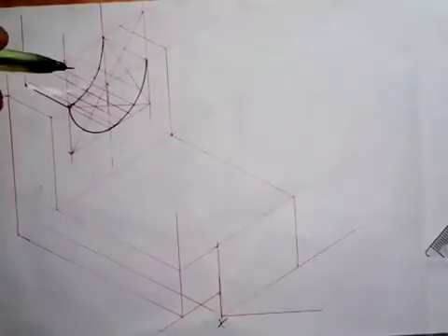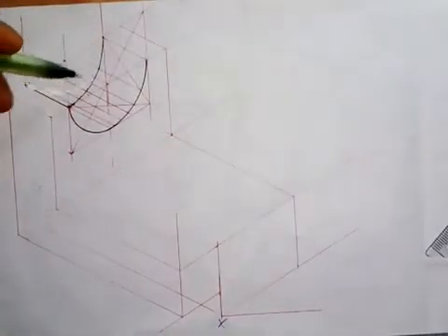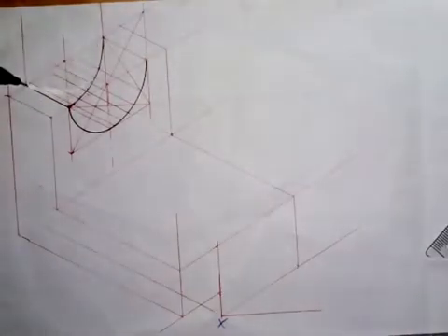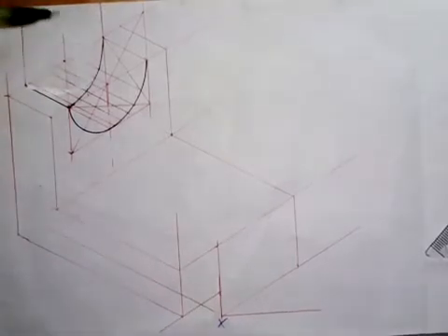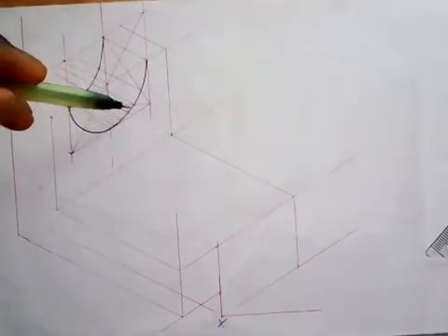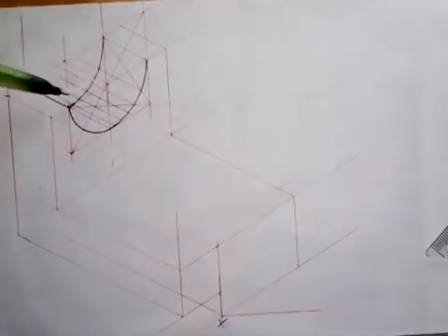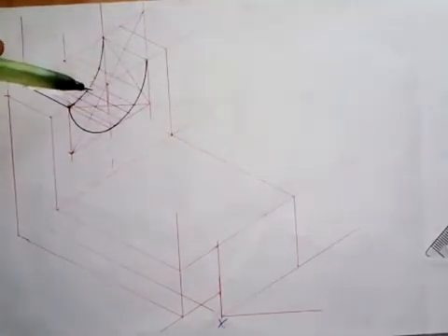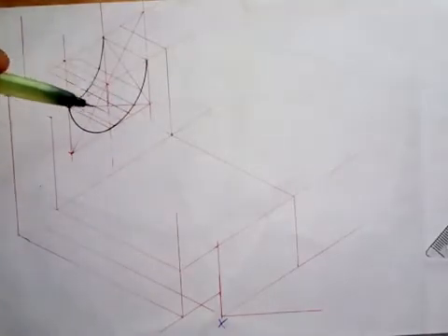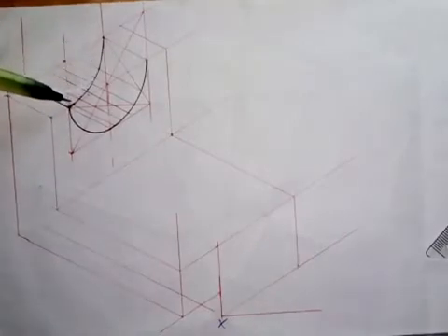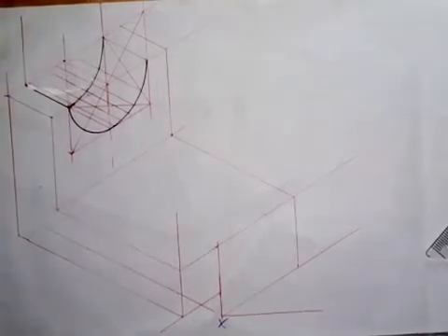As I've said, the other part that I drew here was a mistake. We cannot see the whole of it, we can't see it join this point. So I've corrected it, and what I did is that I drew a line from a point. I took some points on this curve here and transferred them to this side, as you can see the line. Then I take a measurement of 20 millimeters from here to here, 20 millimeters from here to here, and so on for each point. Then I join them together with the use of my French curve. So this is how it's supposed to look. So just take note of that.